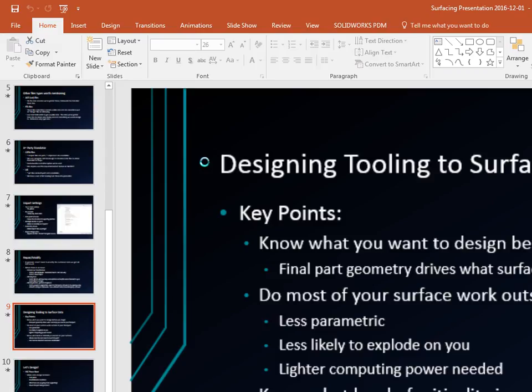Why will a variable radius solve in this case and another one won't? The only reason we've figured out is that the variable radius doesn't care as much about points where you haven't defined it. So it's defined at this point and at this point, but halfway in between it can vary a little bit, I guess. So yeah, variable radius will solve when others won't.